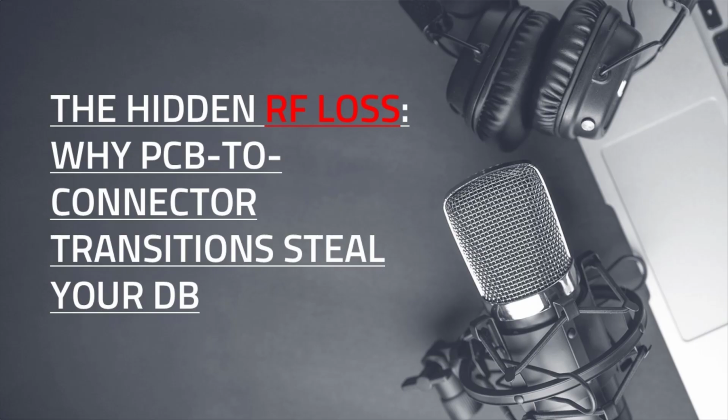So if your product lives in a harsh environment, or it sees vibration, or gets mated and unmated repeatedly, then connector family choice is not only about size and convenience, it's about stability of performance. Two units can measure the same on day 1 and diverge over months, and this is due to mechanical realities that you could actually predict up front.